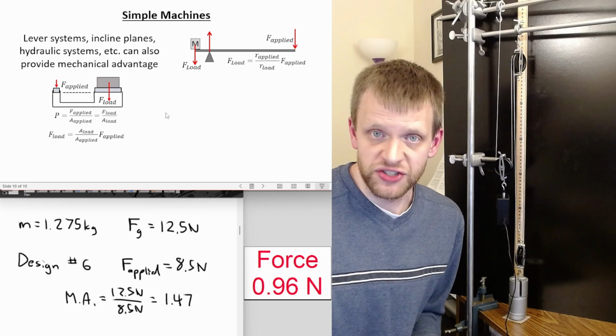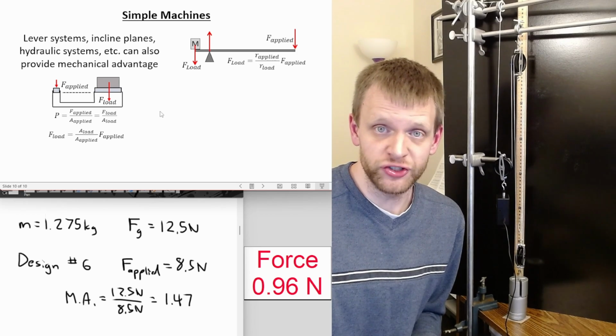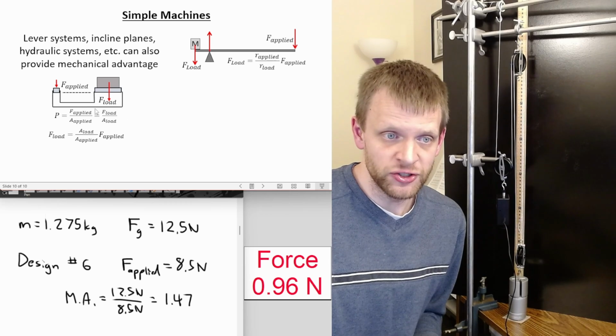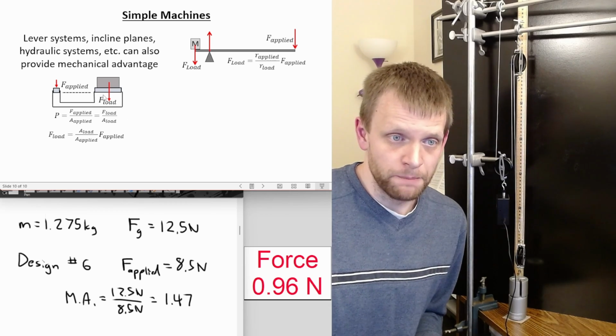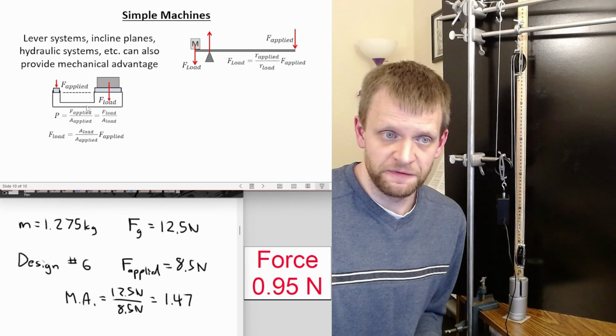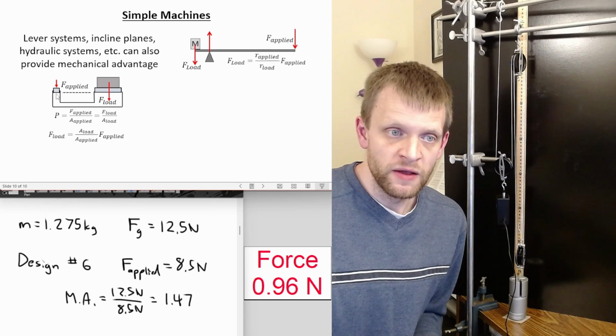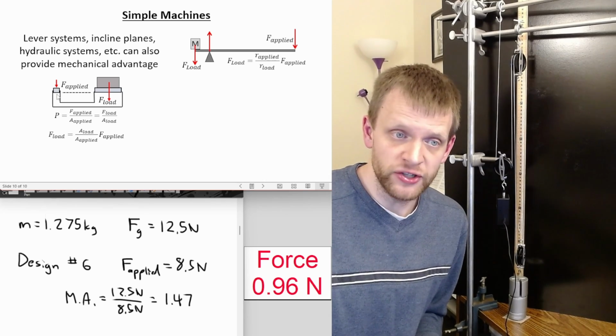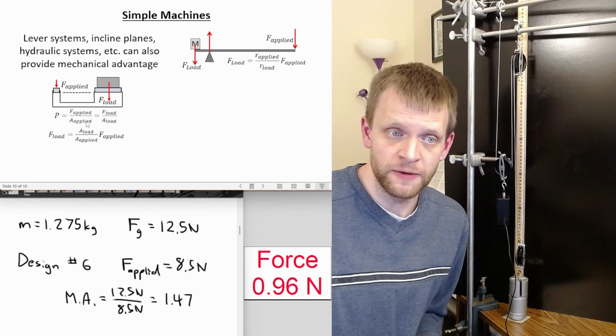For hydraulic systems, systems that use pressure to make a mechanical advantage, well, at the bottom of both of these pistons, let's say this is filled with a fluid, the pressure just underneath these pistons, if they're at approximately the same height, those pressures will be the same. And pressure is force divided by area.